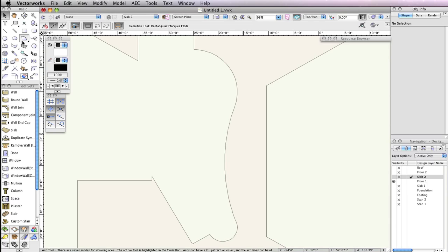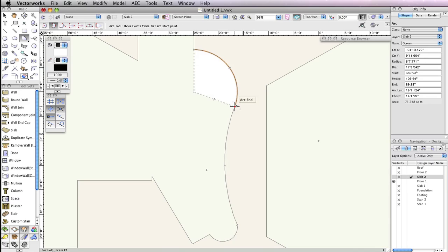select the Arc tool from the basic tool palette and enable the second mode. Click the topmost endpoint of the curve. Next, click the midpoint of that first arc in the curve when the cursor cue Arc appears. Then, click the endpoint of that arc when the cursor cue Arc appears once more to complete the arc. Complete this step 2 more times for the remaining 2 arcs that make up the curve. When you're finished, you should have 3 arcs.